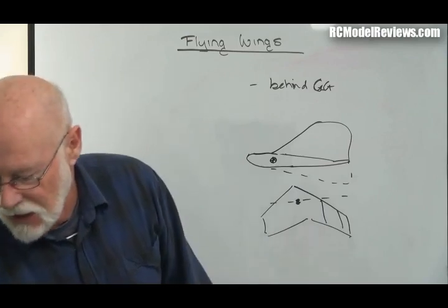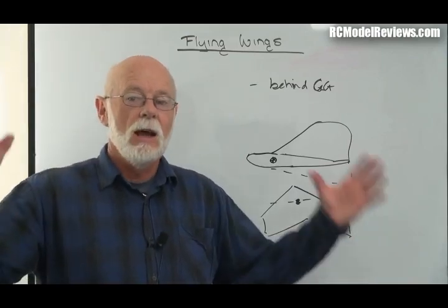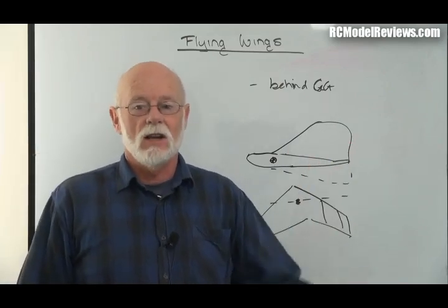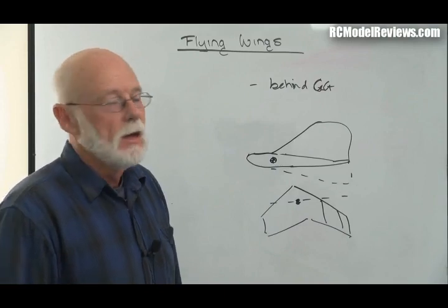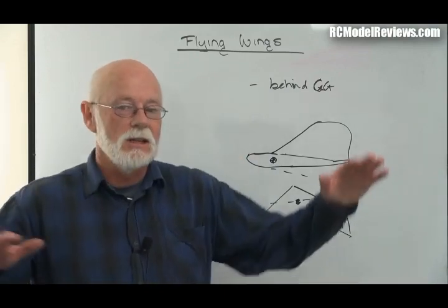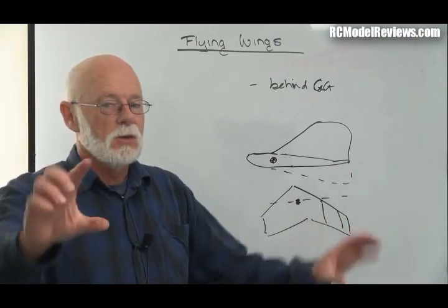And the best thing I can say is get yourself some foam board, cut it up, try out different things. Try planks, try swept wings. Someone's going to ask, what about swept forward wings? Well, that's a whole other video. I'll cover it if you want me to. But suffice to say, I hope I've covered the basics here and I've explained why we get the wibbly-wobbly and one usually pretty simple solution with the wing fences.